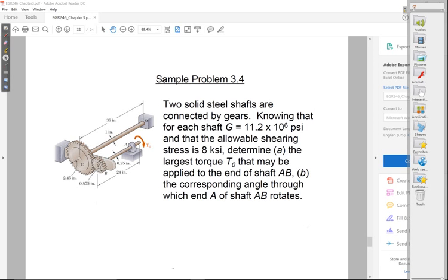D could be driving some tool, and there's some resistance at D. So keep in mind that even if these two shafts are rotating at a constant speed, that's very similar to a case like this where we have static equilibrium. You will work it out the exact same way. So don't worry too much about the practical application of this. All right, so that's the first thing.